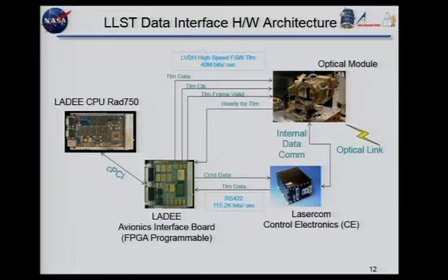One of the challenges with the lasercom serial interface was they had like a 16-byte buffer. So we had the flow control issue, where I couldn't send commands to them too quickly because it would overflow their buffer and they would just miss the command. So they had a software signal coming back saying, okay, I'm ready for the next command.